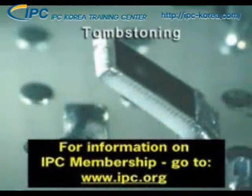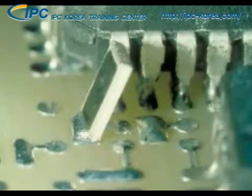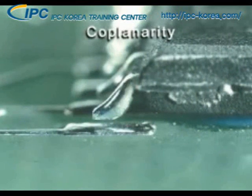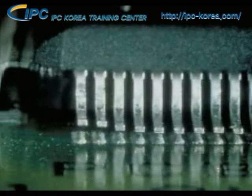Tombstoning is a defect that's specific to chip components. Notice how one end of the component termination is completely lifted off the land. Tombstoning also interrupts the electronic signal and needs to be fixed. On the other hand, coplanarity is specific to J-leads and gull wings. This defect occurs when one lead, or a series of leads, is out of alignment and fails to make contact with the land. If there is no electrical contact, this condition will need to be repaired or reworked.